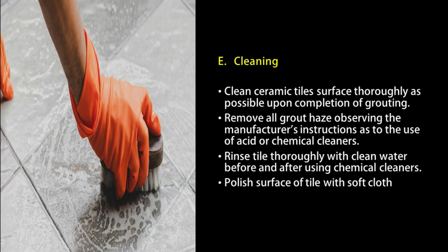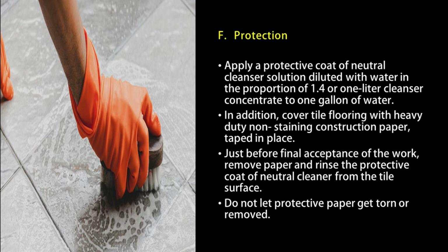Cleaning. Clean the ceramic tile surface as thoroughly as possible upon completion of grouting. Remove all grout haze, observing the manufacturer's instructions as to the use of acid or chemical cleaners. Rinse tile thoroughly with clean water before and after using chemical cleaners. Polish the surface of the tile with a soft cloth.